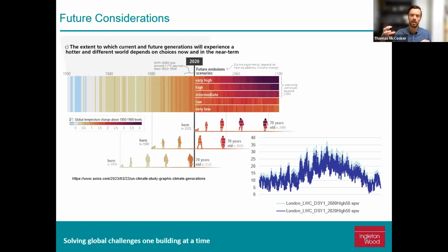So even if you bring in that external air during the day, you can't get the temperature inside down any further, which is why we have to think about these interventions, those 5 things I mentioned earlier, with the thermal mass, with the ventilation, integrating those two together, minimizing solar gain, having a really concerted effort on trying to reduce the load in the building, reduce those internal gains and reduce the temperatures first and foremost, so that we can use that cooler nighttime air, even if it's only a couple degrees cooler, to just bring that whole mass down and allow for a cooler temperature during the day.